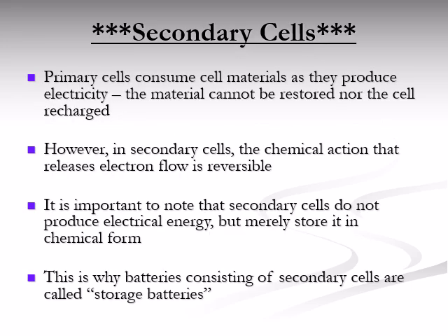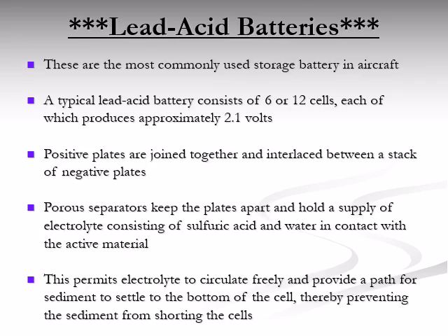Unlike primary cells, secondary cells can be recharged. They don't generate electricity, but store it chemically, hence the term storage batteries. Lead-acid batteries are common in aircraft. Each cell gives about 2.1 volts. Plates are immersed in sulfuric acid and separated by porous material to allow fluid movement and sediment collection.